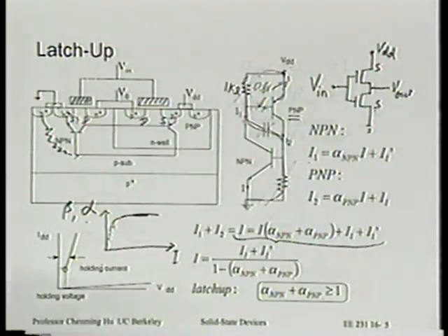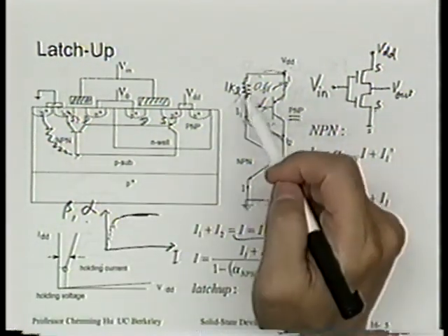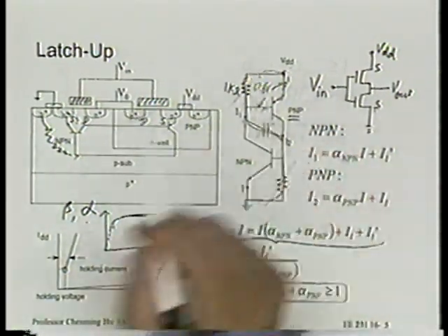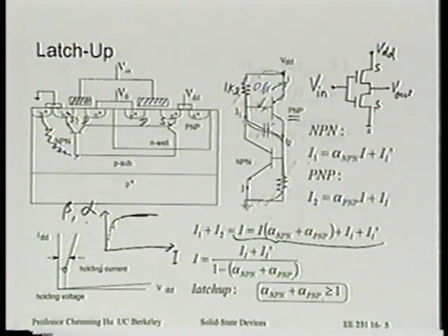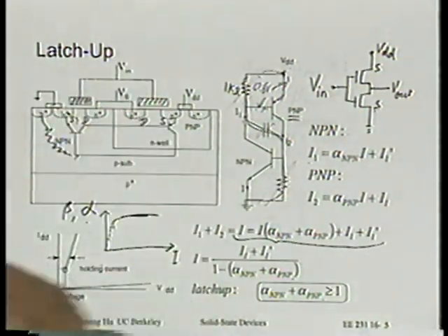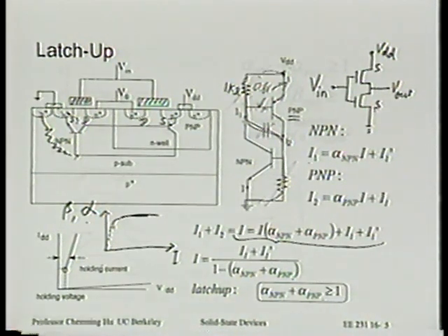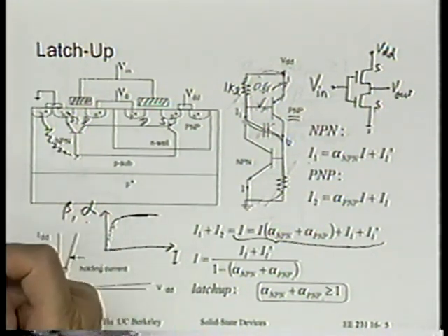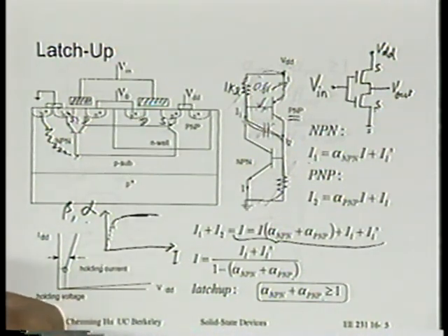So here's the question for you. Given that's the answer, is it good enough if we have a 1 kilo ohm here? Is that small enough? No, because 0.6 milliamp is not that large a current in terms of transients in the circuits. I give you an example. We want to tolerate an ampere of trigger current. Turns out we cannot do that either. So a very typical spec for trigger current in the company these days will be things like, say, 200 milliamp or something like that. You have to be able to tolerate that kind of trigger current before the transistor goes into latch up. All right? Okay?